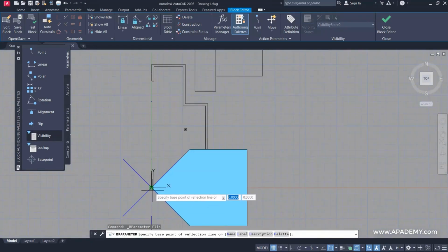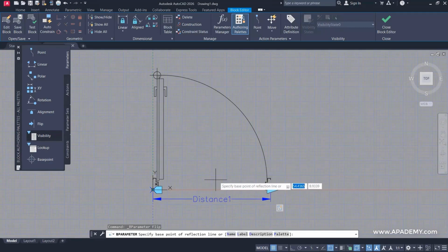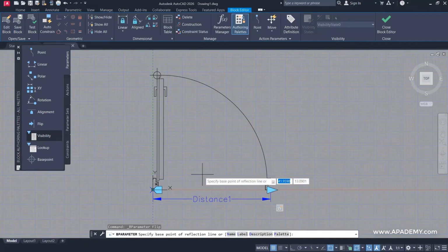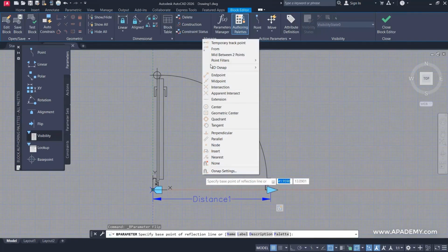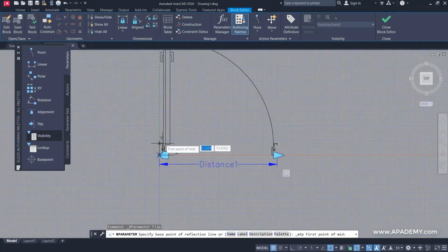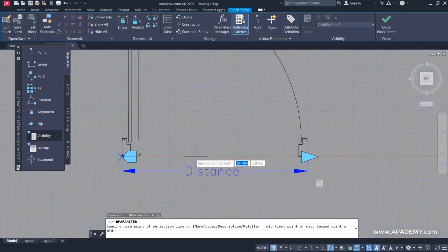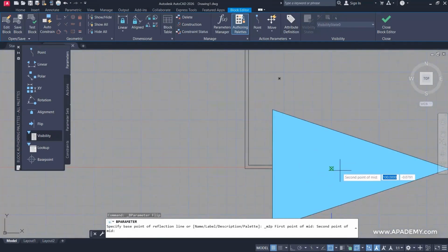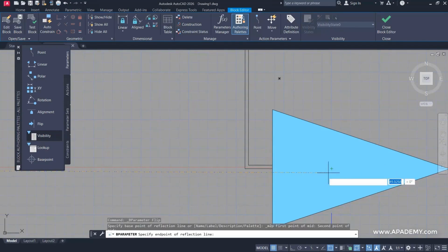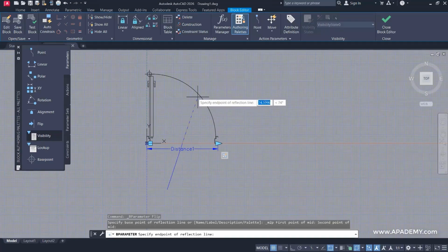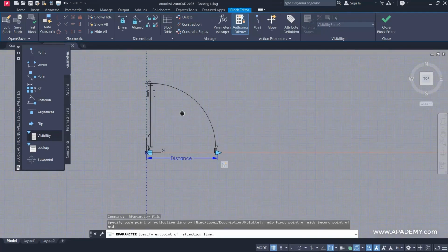So we come and want to select the center of this. Now, let's consider a point down here and a point up there. How do we figure out where the middle of these 2 points is? Hold Shift, right-click, and select mid between 2 points. It creates a point between these two. And it selects this. So, between these two, it ends up here. These two selections I made give me the midpoint.